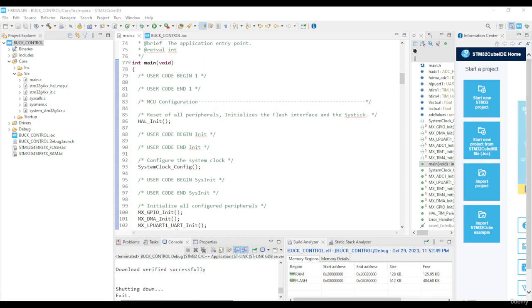Of course, using this on a different microcontroller system, like another family, for example NXP or Texas Instruments, you would have to initialize the peripherals differently there. But coding the actual control system is a lot easier because you're basically just going to copy and paste a certain file and change the duty cycle update, and of course the ADC aspect, updating it from the DMA as you should. But that's about it.